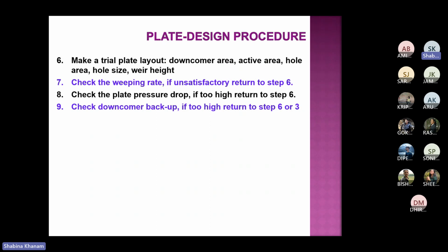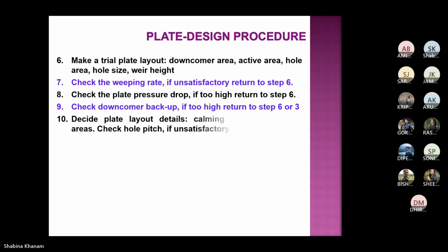We need to consider downcomer backup. If too high, again step 6 or 3. Step 3 is where we have decided plate spacing. Next, we need to decide the layout design, like over the plate, what is the calming zone, perforated area, and check for hole pitch or hole spacing, the same thing. If unsatisfactory, return to step 6.